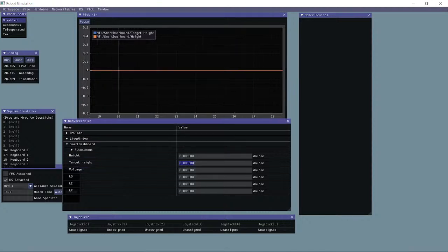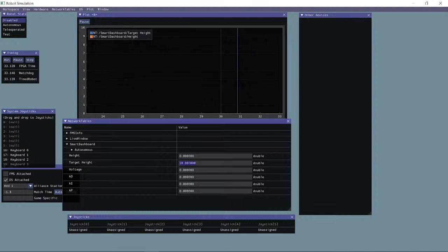I just start by setting this to 10 and then back down to 3 or 5, so you can see the graph. If I start off with KP at 0, obviously it's not doing anything. Zeros for everything is always the first step. Make it 1 though, and I get this incredibly slow response. Then you can bump it up from here, and it doesn't even reach the target because there's some gravity acting. And I could use Ki here.